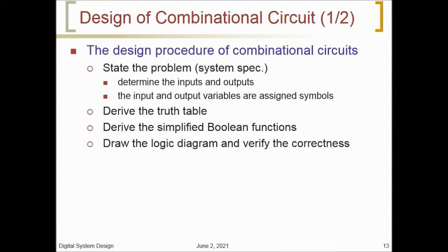Practical design must consider such constraints as the number of gates, number of inputs to a gate, propagation time of the signal through the gates, number of interconnections, limitation of the driving capability of each gate, and various other criteria that must be taken into consideration when designing integrated circuits.